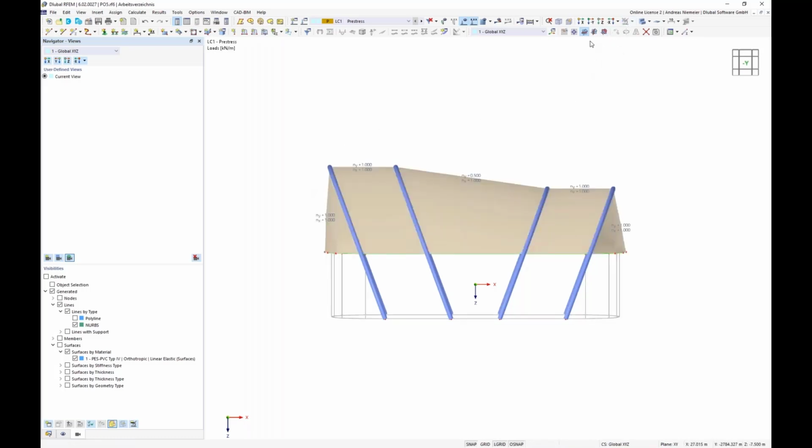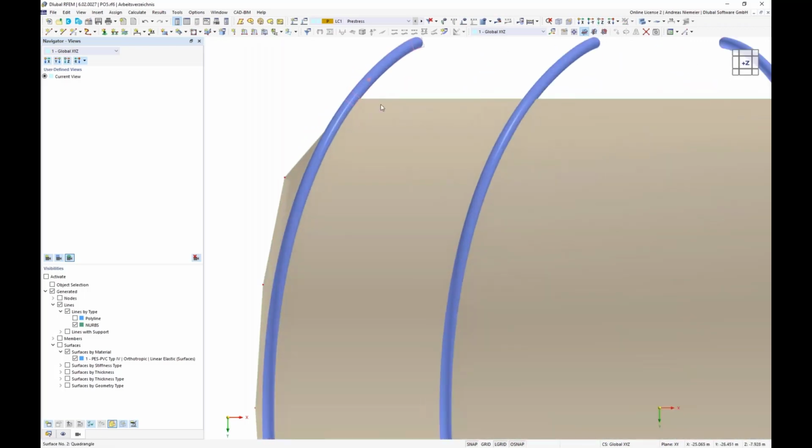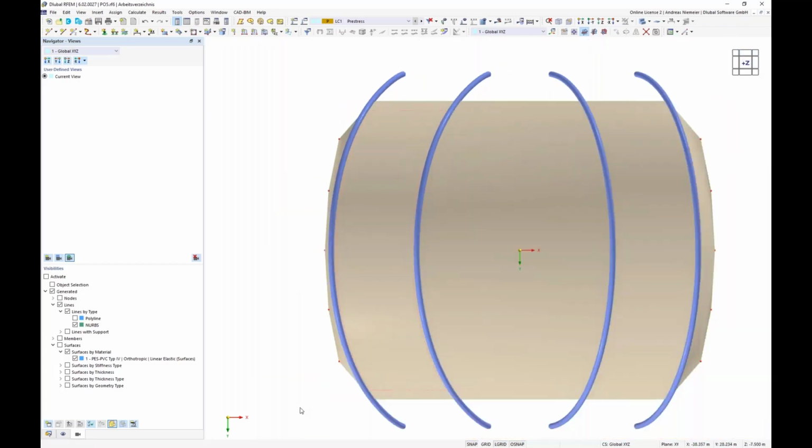But when we take a closer look here, you will see that we will run into an issue because the membrane edge is exactly on the place where this linking beam should come. So for solving this issue, we have to produce a situation where you can have a straight line between these two definition nodes, and later we can connect the cable on another place.